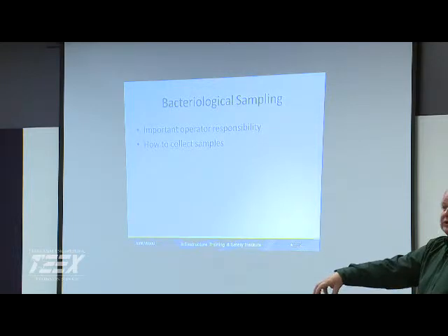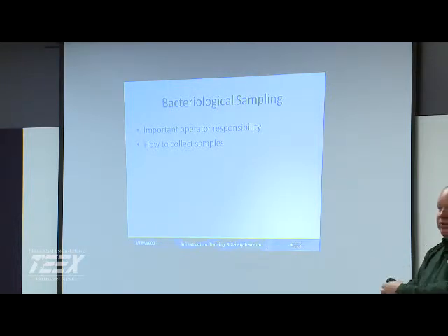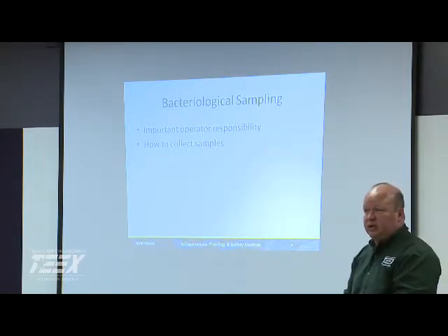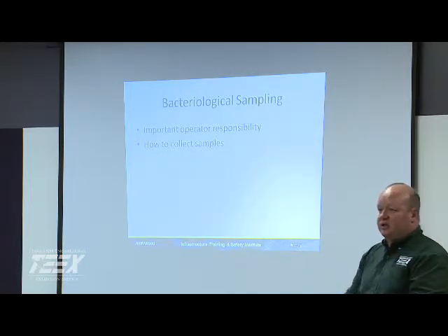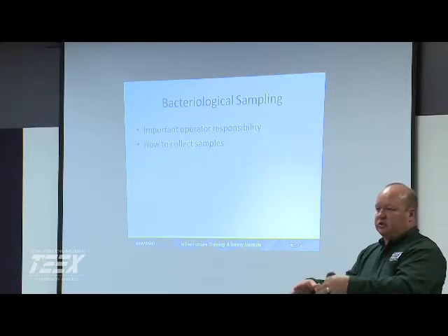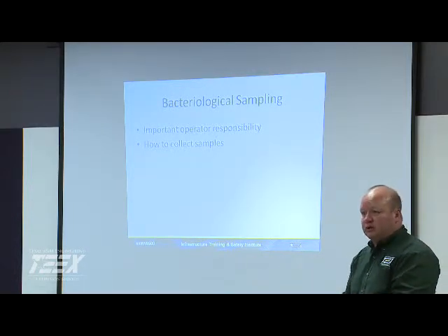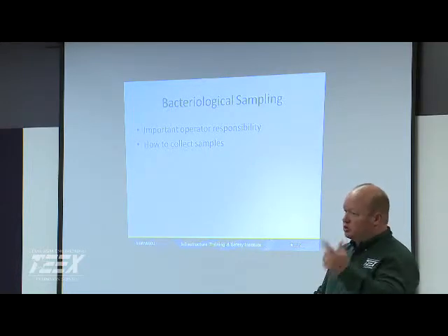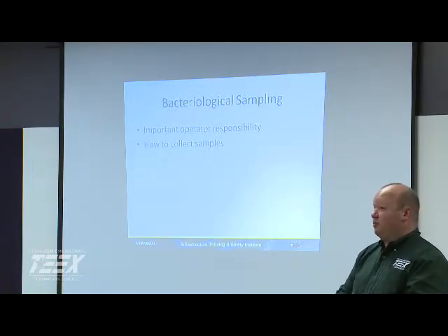Even something as simple as how you transport them. You stick them down in ice. You put them in a plastic bag before you put them in the ice. Do you have the blue freezer packs or something like that? Because you can potentially contaminate that sample bottle. If you have an ice chest, the ice is starting to melt, it's floating around in there, you've got your bottles dropped down in there. So those are just things to think about when you're asking, how do you preserve your samples? How do you preserve the integrity